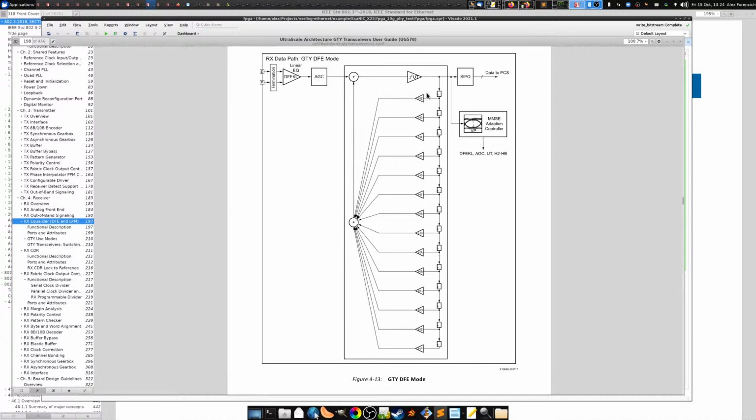So what happens here is if this was 0 here, then this will produce a large positive offset, right? That will push this up over the sample point. So this will read as 1, right? That'll get stored here on the next cycle. That'll then produce a large negative value, which will push the sample point down. It'll read as low, and it'll put a sample point down, so it'll read as high, and then it will oscillate, right? So every other cycle, this will go high, low, high, low, high, low, and this will produce some bit pattern.